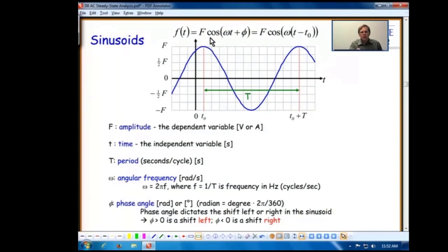However, usually we approach a problem by working at one frequency at a time, so we model everything as a phasor representation, which we'll get into pretty soon, which is essentially a vector having a magnitude and phase. And then we can do algebra on complex numbers, and that allows us to determine how components that have a differential relationship between voltage and current, and would ordinarily require differential equations to solve, we do with complex algebra instead.